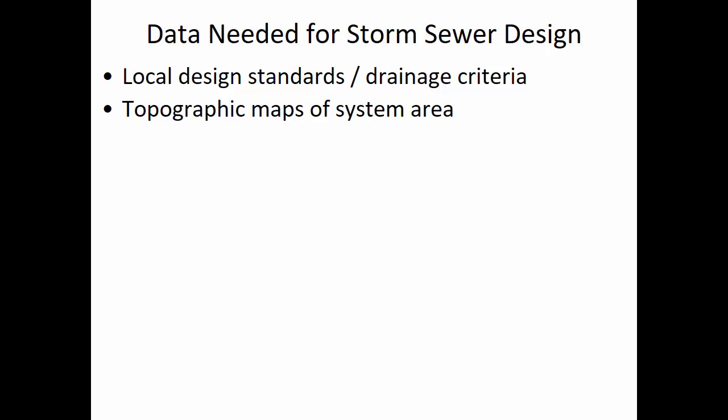are in use. There are some really flat areas, for example, that maybe just because they have no choice would allow contractors to lay wastewater pipes at a slope that's relatively flat, and other places that have a little bit more relief, a greater elevation difference as the ground is sloping towards a river or the stream, or wherever the downstream receiving body is. If they've got more relief, then they wouldn't allow the slopes to be quite as flat, just because it's really challenging and you need a contractor with a lot of skill to lay a pipe out on a relatively shallow slope.